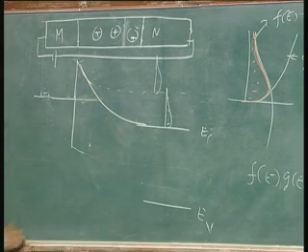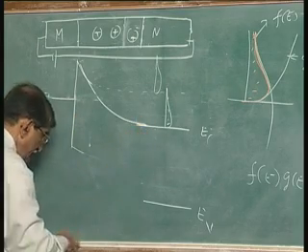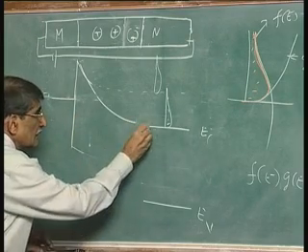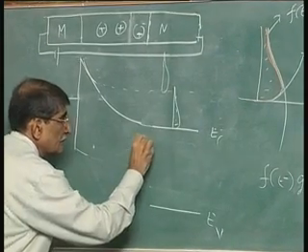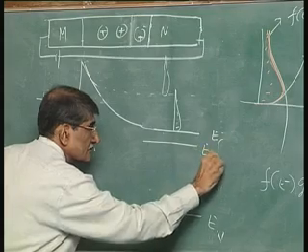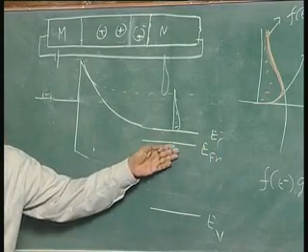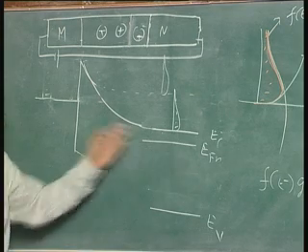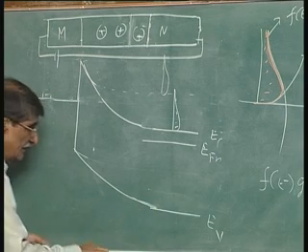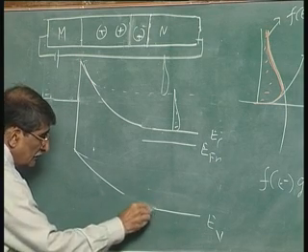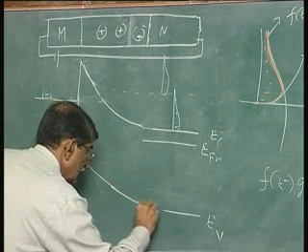And you can't draw the Fermi level here now. You draw it only there and call it the quasi Fermi level. It means you can still compute the electron density using this Fermi level with respect to the conduction band. That is the meaning of quasi. You do not talk about that here. And from here, the whole thing comes down. Okay. So that is the new energy band diagram.